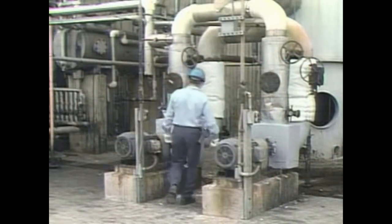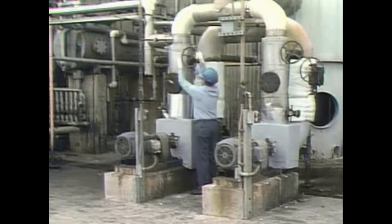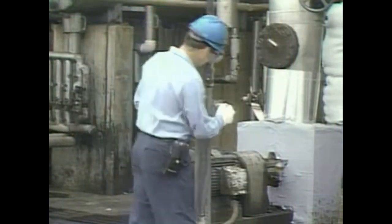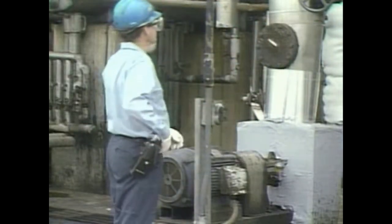Once the operator chooses the pump, he closes the drain valve and opens the suction and discharge valves for that pump. This procedure is known as lining up the valves. He also lines up the valves for the standby pump according to operating guidelines. He then starts the pump that he's chosen for a moment to make sure that it's operational.